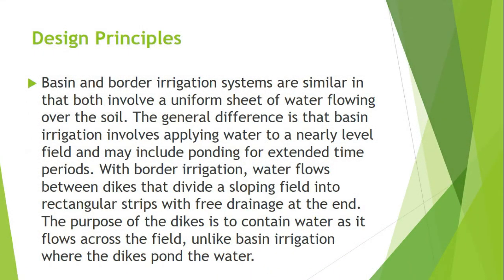Now I will talk about the design principles and the design steps or the methodology of the basin irrigation system. First, let's talk about the design principles of the basin irrigation. Basin irrigation is a class of surface irrigation methods in which the area is divided into basins.